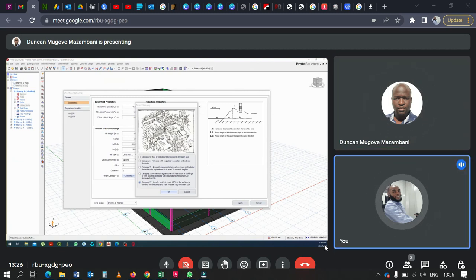But if you want to build around a forest, like a village or rural area, where you see bungalows, 1-story buildings and bushes, then if you build your 4-story building, there is a tendency that the wind effect will be much on your building, because around that terrain there are no tall buildings up to your own standard. So you have to pick your option here. We always pick a worst condition if you don't know the place where it is to be built. But for you to be designing, you should be able to know the building location.